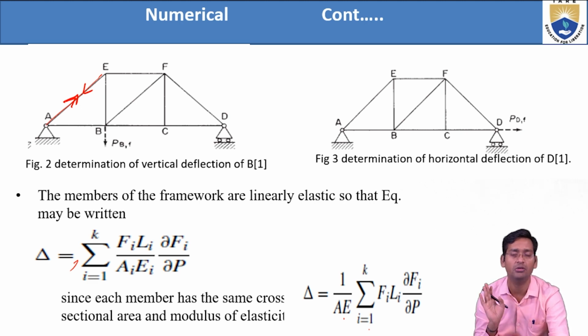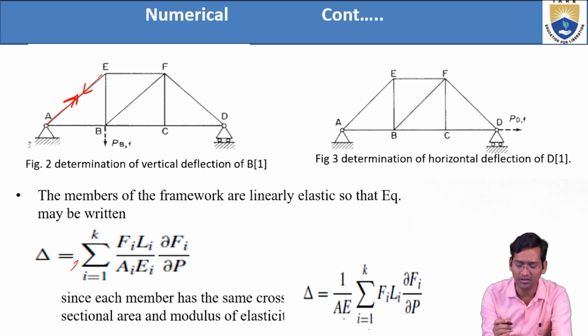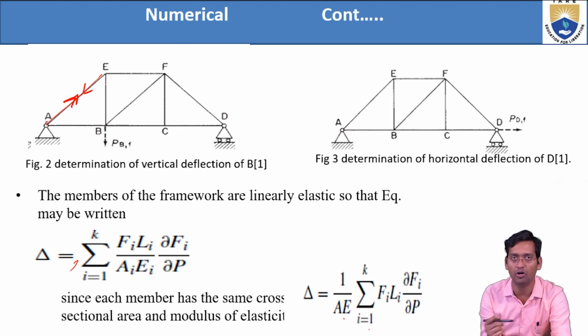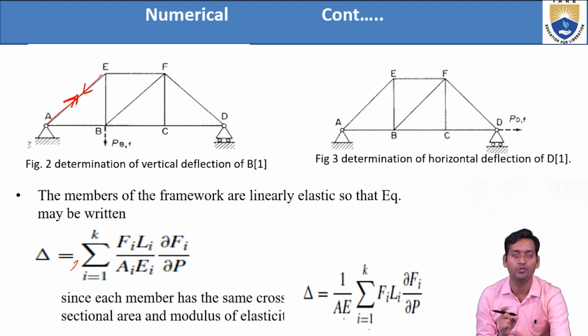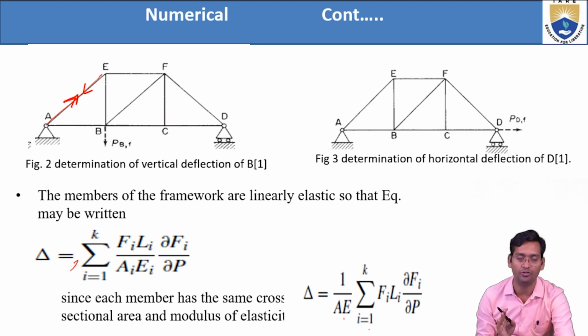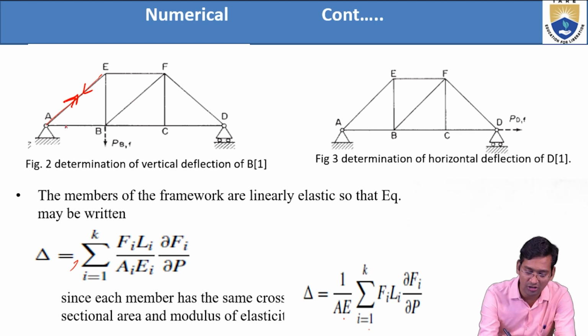If it's positive, then it's elongation. So now we got the negative for AE, so AE is getting compressed, and AB we got positive, so AB is getting elongated, or AB experiences tension, right? So don't get confused here with the negative and positive sign. That is just to check whether a compressive or tensile force is acting on that member. Okay, so now we got these two.